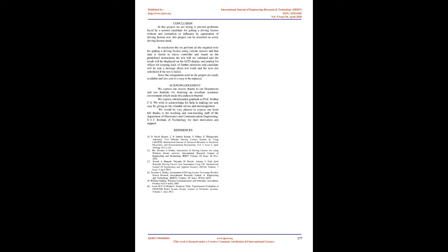The SIM900A is a complete dual-band GSM/GPRS solution in an SMT module which can be embedded in customer applications. Featuring an industry-standard interface, the SIM900A delivers GSM/GPRS 900/1800 MHz performance for voice, SMS, data, and fax in a small form factor and with low power consumption. With a tiny configuration of 24mm x 24mm x 3mm, the SIM900A can fit in almost all the space requirements in user applications, especially for slim and compact design demands.